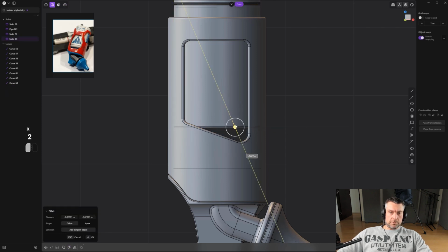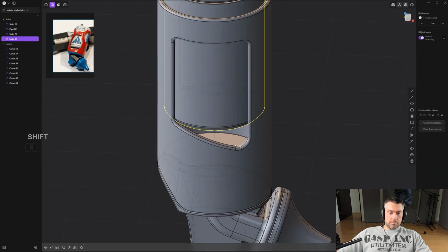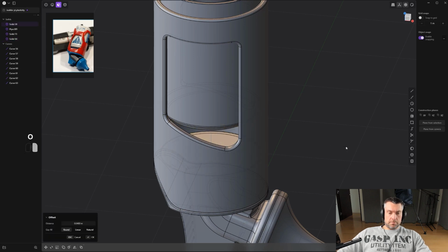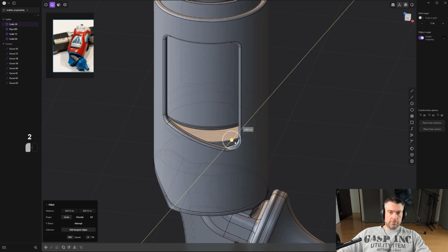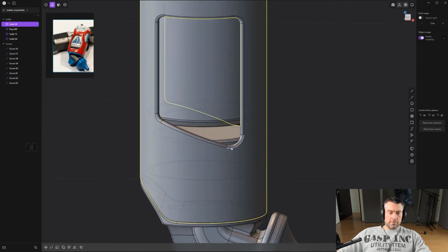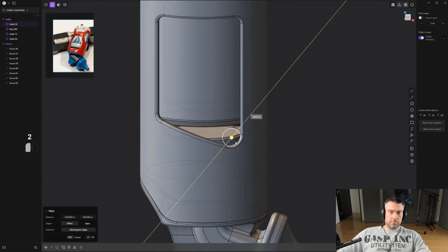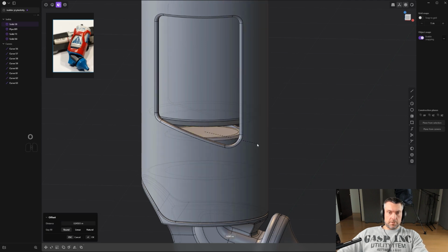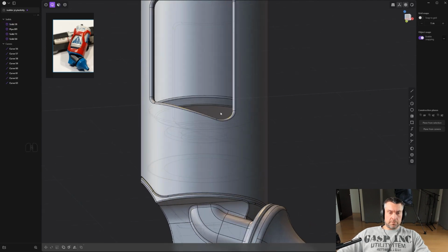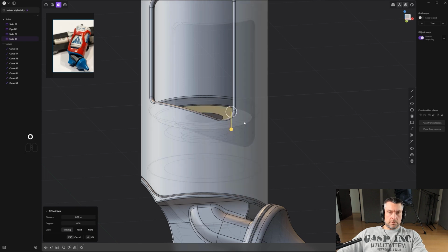this thing here. Let's just chamfer this and then create two bevels. And then what we're gonna do is we're going to grab this face, move it up like this. I want to chamfer it, small chamfer. And then, in fact, let's just make this face a bit smaller. One time chamfer here. Select the face in the middle, and we're gonna create this kind of like a pin in the middle, right? So, something that goes in, whatnot, and delivers the goods.